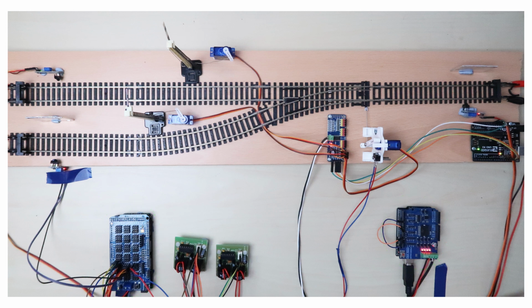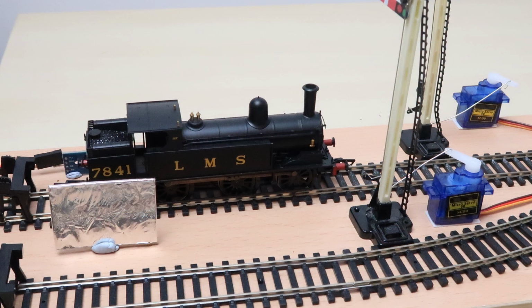As you can see, even for a very small layout, we've got 7 sensors, 3 servos and a lot of wiring. I'm using 3 Arduinos, each with their own USB connection. One for the servos, one for the sensors and one for the base station. It might be possible to combine the sensors and the servos, for example, to save on space, cost and USB connections, but I prefer to keep the systems separate because if anything goes wrong, then I know exactly which board to focus on. The only other thing I need is a loco, so here's my Bachmann Webb coal tank ready to run. That's the physical layout, now onto the software.